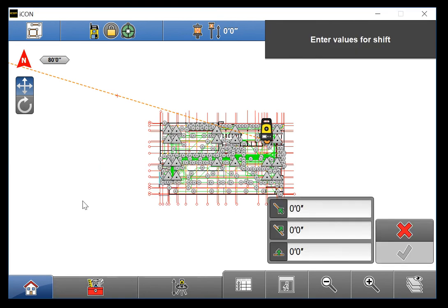When properly used, this option allows us to store a point at a specific distance from the point being measured by the total station. This can be covered more in hands-on training, but I will give you one example. If I'm trying to record the face of a wall that has 5/8 drywall in front of it while using reflectorless prism mode, I can offset the measurement by those 5/8 of an inch to achieve the true measurement.